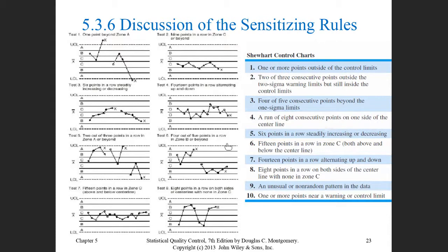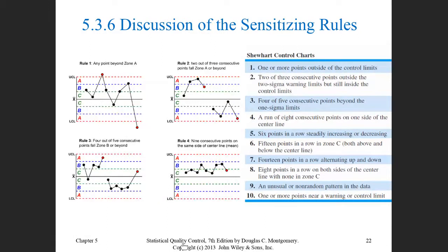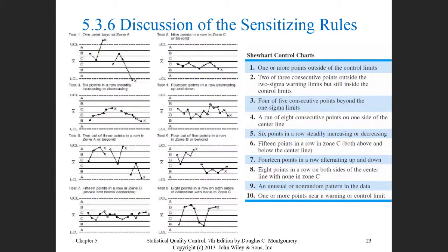A question like this could give you an example of a control chart with an event and ask you to identify what type of event is stated in the illustrated picture. So a picture could show you one of those examples here or in the previous ones, and ask you to identify what the violation is, or what the points needing attention are. So you have to state the rule that matches the figure.